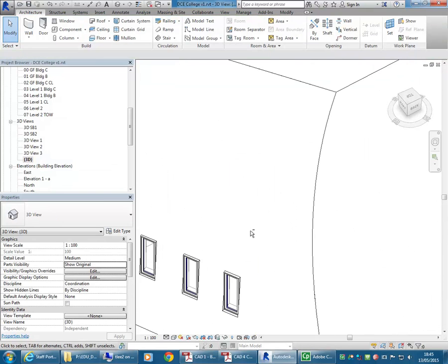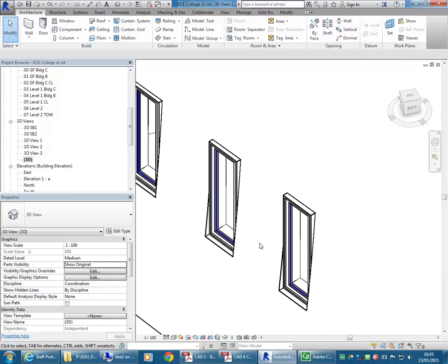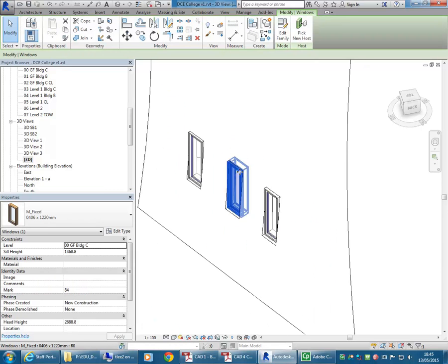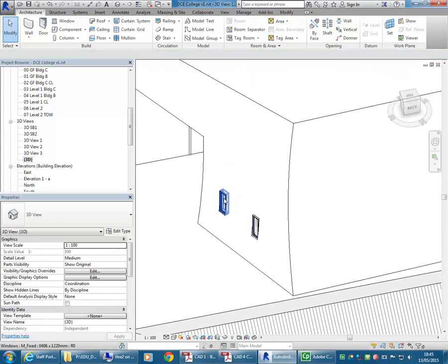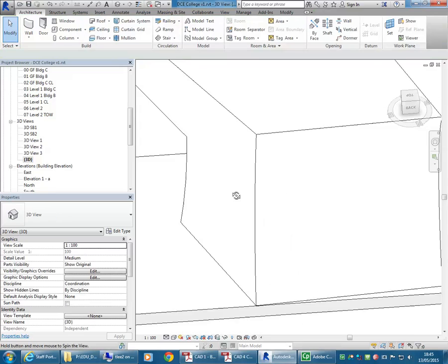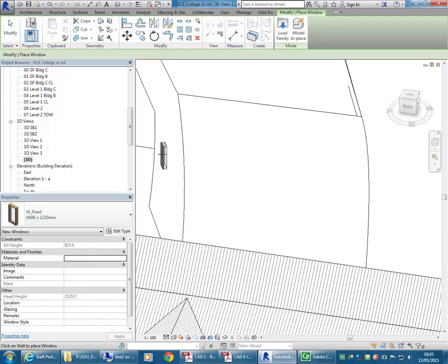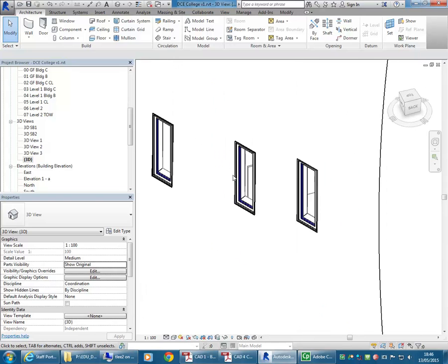So you've got to check that the slope works. You can see there those windows then starting to have issues because they're projecting out from that surface. In this case you'd have to make a different window family if you wanted to place a window there, but you'd probably think about where the windows would go into a wall like that and maybe place them into a part that's not sloping so much. So that's a lot better.